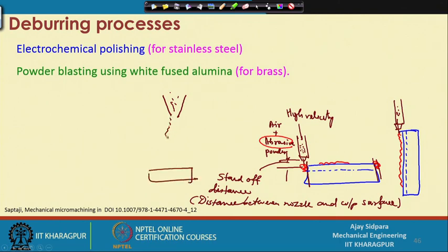What is going to happen is that this abrasive particle stream spreads. Whatever the zone is coming here will spread in this location, and the velocity will reduce as soon as it reaches the surface. So, you do not have dimensional control; only this particular region is there where you can expect that the diameter of the nozzle is the same as the area where your abrasive will strike. If this is the case, you may get a reasonably good amount of removal of these burrs, but as soon as it is passing through this location, nothing is going to happen, and the particles will be spread away. So, you can understand the removal of the top burr is difficult compared to the entrance burr and the exit burr.